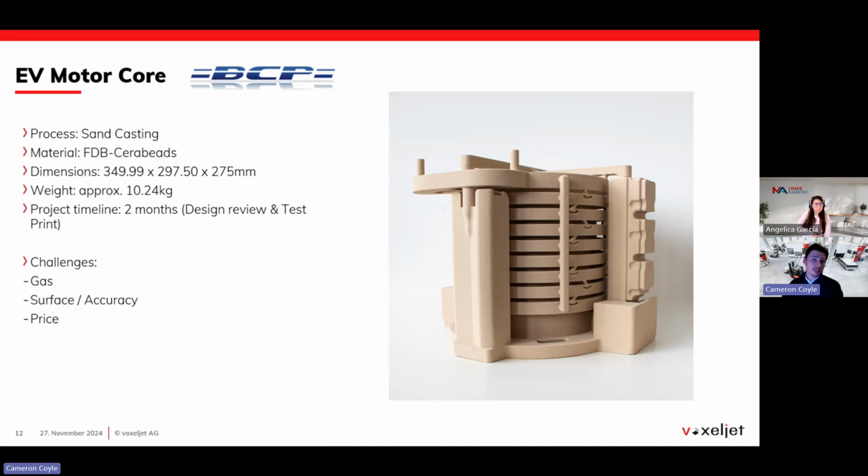Through this project with the customer, we worked with them for around 2 months to test and validate the process and different design ideas in order to solve some of the problems that they were having. When the customer came to us, they actually first came with only the water jacket as a single core and not all of these additional features which you see today. Now, when they had this first version, just the water jacket, it creates a very fragile core. We have to send that from Germany to the UK, and it made it quite difficult to handle that part and ensure that it arrives in a good condition.